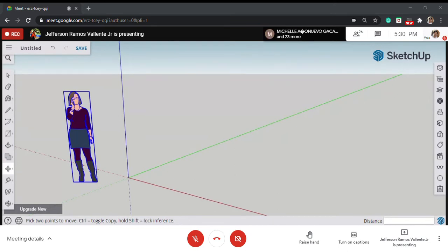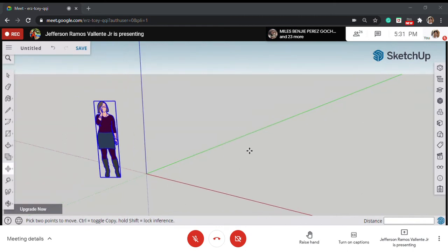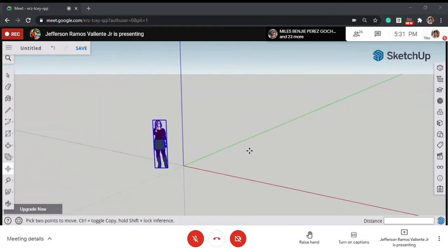Okay, go ahead. So when you start your drawing, let's just say that in this exercise, you're using a 9x7 house. So 9x7 is 54 square meters. Medyo small, but these are the sizes in subdivisions. So we'll start with the rectangle. When you use the rectangle function, you can either use the panels here on the left. So go and find the rectangle part here, or just press R on the keyboard. That means rectangle. And when you draw, start from the origin.